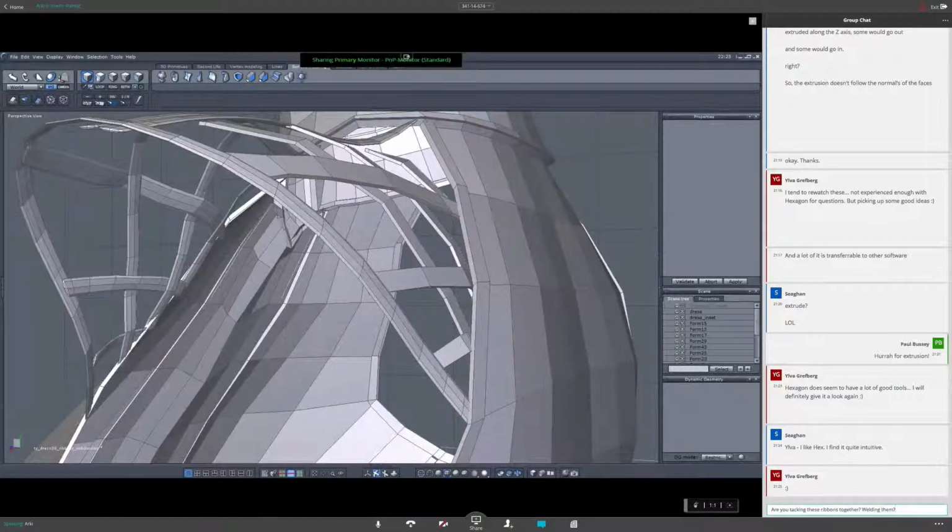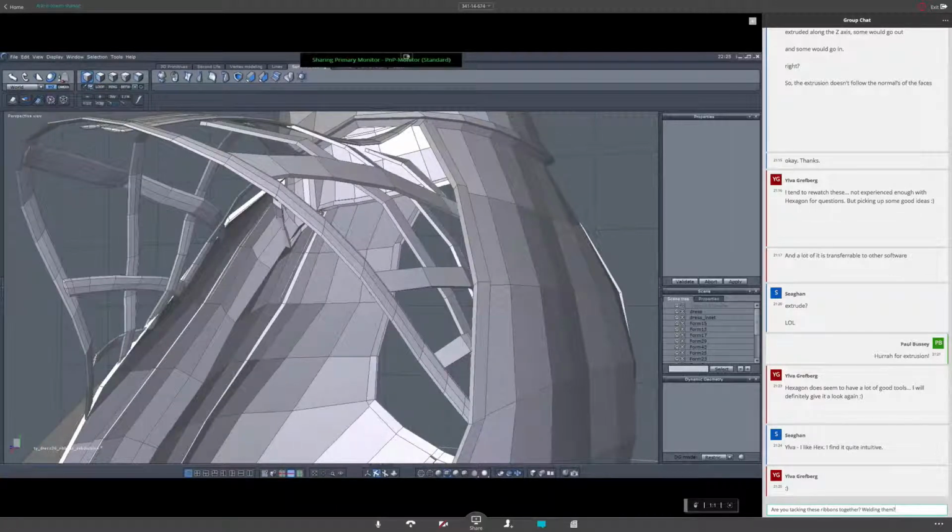All of these here. And these might cause you some trouble inside of DAZ Studio because the way DAZ Studio works with AutoFit, adapting your dress to a new body shape, it might push this underlayer through the layer on top, and then you will get render artifacts. So I think the best idea is to delete all these ribbons on the underside. Don't go for two-sided objects when you create clothing that uses AutoFit. It's a good rule, it saves you a lot of headache.